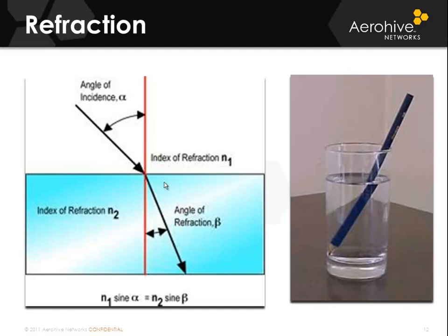An indoor environment is less likely to suffer from refraction due to being in a controlled climate. Outdoor environments are going to be the ones that normally suffer from this more, because the RF signals typically refract slightly back down towards the Earth's surface. However, changes in the atmosphere may cause the signal to bend away from the Earth, and in long-distance outdoor wireless bridges, refraction can be an issue. An RF signal may also refract through certain types of glass and other materials that are found in an indoor environment.